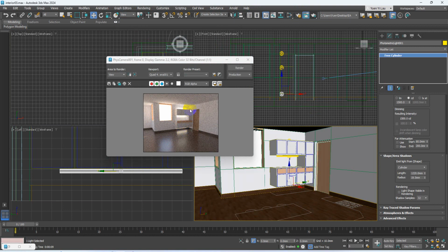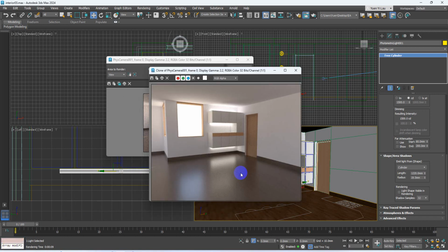This is a very draft rendering, so it takes just 9 seconds, with a lot of noise and the resolution is not enough. This sample, I've put this picture into Moodle. I spent about 7 minutes to do this render. You may have a try for your render. Try to add some light to your scene and try to change different kinds of material, because the material will affect the time of rendering a lot.